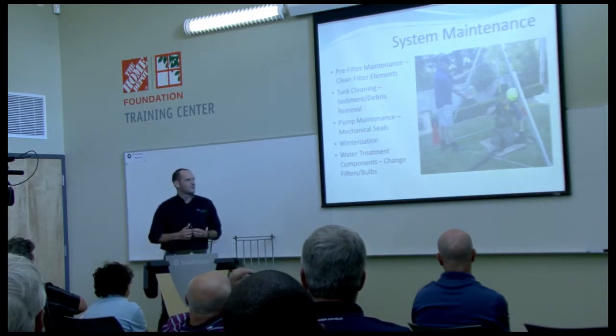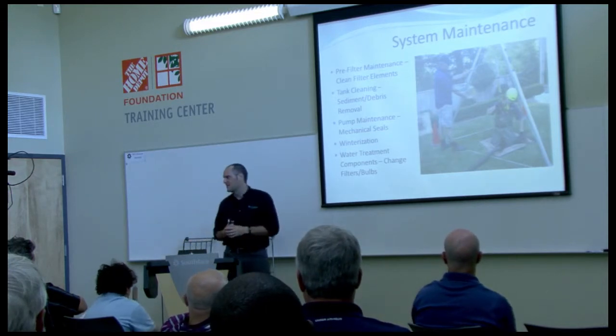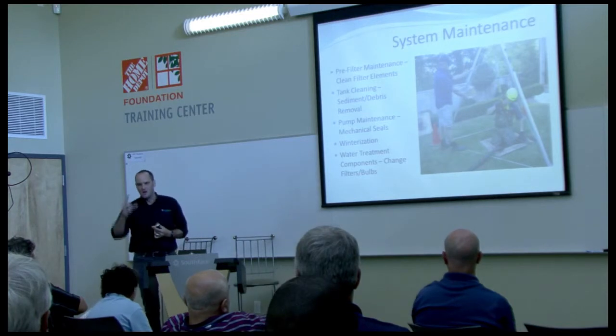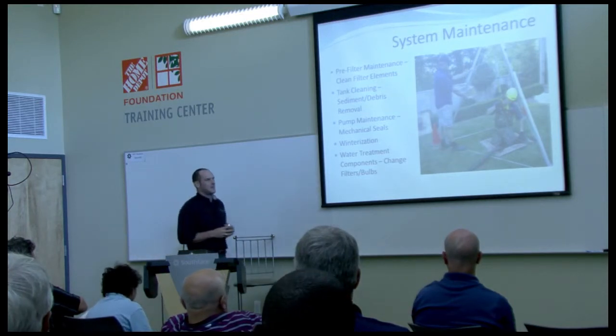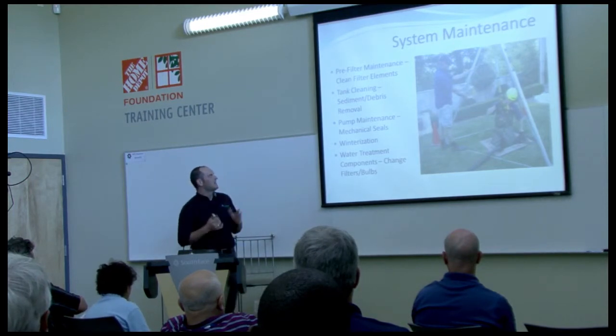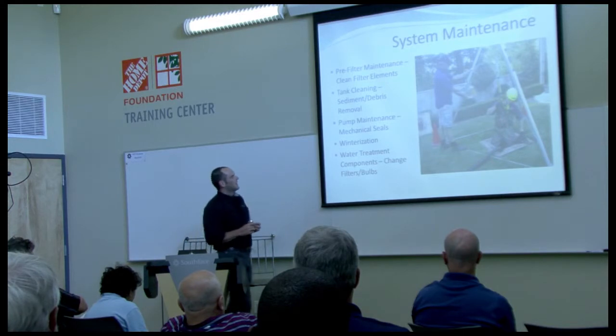Occasionally you'll have tank cleaning, although you'd be surprised how infrequently it is. A lot of these systems that have been installed in Atlanta have been in for 5, 6, 7 years, and probably the tanks have never really been cleaned out. All that's really forming down in there is that sediment bed on the bottom, and it's not that detrimental to the system as long as you're treating it right. But occasionally you would have to clean your tank out.